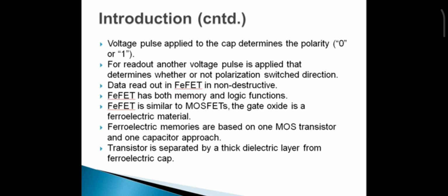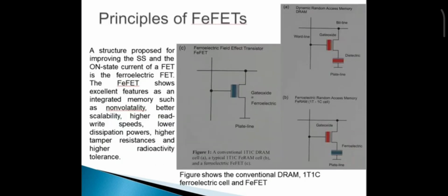Ferroelectric memories are based on the MOS transistor and one capacitor approach. We will discuss that in the next slide. The transistor is separated by a thick dielectric layer from the ferroelectric gate. Next is the principle of the ferroelectric field effect transistor.